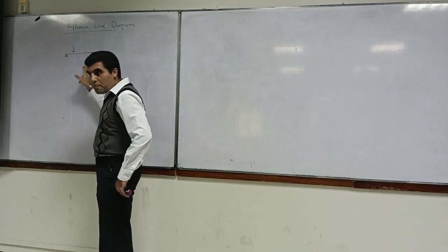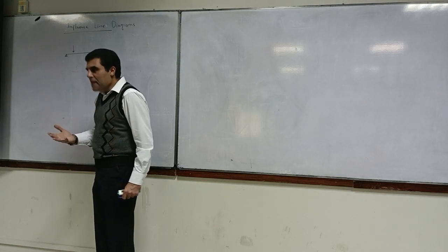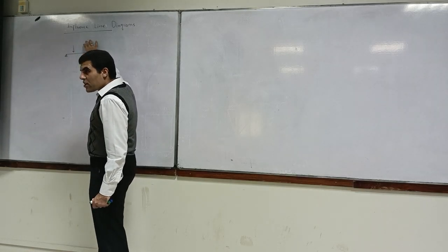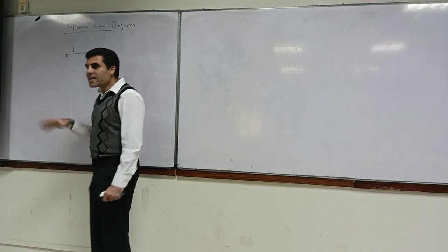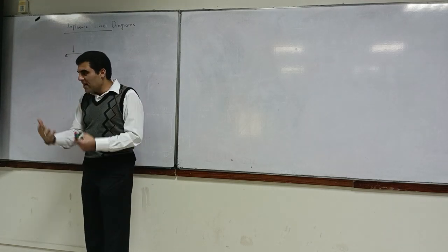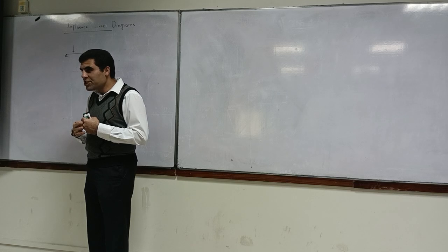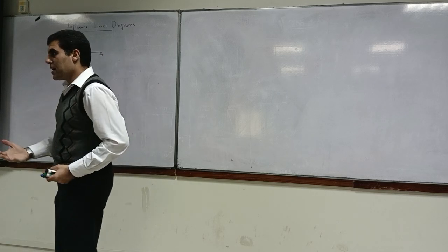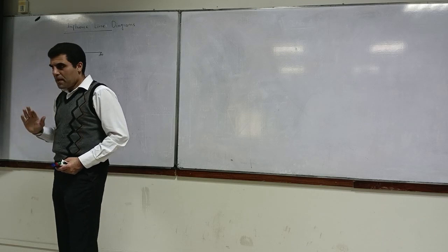Okay, so what happens is that, I mean, that is very time consuming, isn't it? So something called influence line diagrams then come to our rescue. It gives us a picture, it tells us what the magnitude of a particular quantity of interest would be when your load is moving.